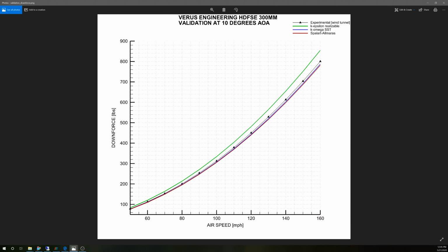There are different types of K omega SST models, like the Menter, and a bunch of other ones. A lot of people spend a lot of time on turbulence models, and that's what's really key to getting good CFD. It's very critical when you're talking about cars and just general bluff bodies, because that's how you know when separation occurs, and if you capture separation properly, you're going to get better downforce data, you're going to get better drag data. Some models are better for downforce, some models are better for drag capture, and all of those things.